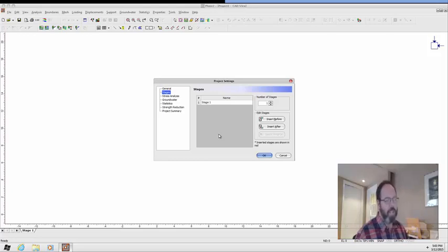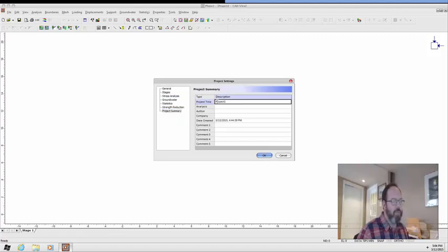And you could, for instance, a stage could represent adding a load to a boundary or excavating another tunnel, or perhaps you're going to excavate a stope in multiple sub-stages. So I'm going to use 2 stages in this case. And the rest of the analyses settings, project settings will stay the same. In project settings, you can put a title in for your project. And you can put your company and so on. And a number of other comments.